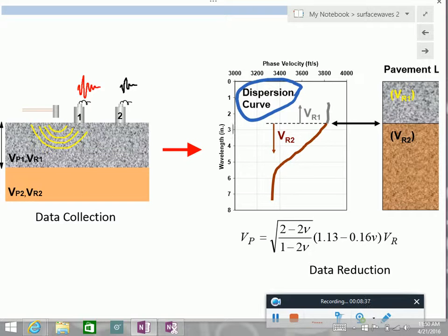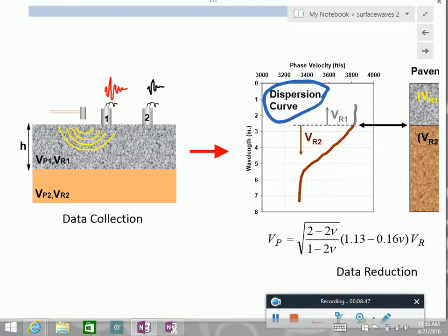So we have a layer of concrete over a layer of soil with wave velocities VR1 and VR2. The hammer is creating different frequency components, so different waves of different frequency are going to propagate. Let's first think about the high frequency components. A hammer creates different components at the same time. It has a broad range of frequencies, a broad spectrum. Okay, is this clear for everyone?